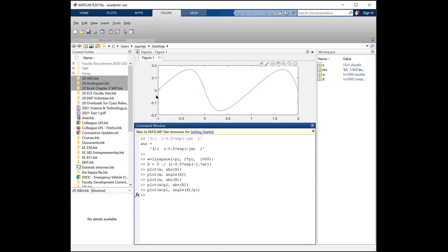on the horizontal axis. Its vertical amount is the angle of its DTFT, and you can see it never comes close to a full pi, so it doesn't want to wrap around. If it did look like it wrapped around, if all of a sudden you see it suddenly changing from +1 to -1, you could always unwrap it. You could do something like this. Unwrap your angle. Here it obviously doesn't do anything. And if you prefer to have your angle shown in degrees, you could just simply multiply that by 180 over pi. And now you can see what your angle is in degrees.